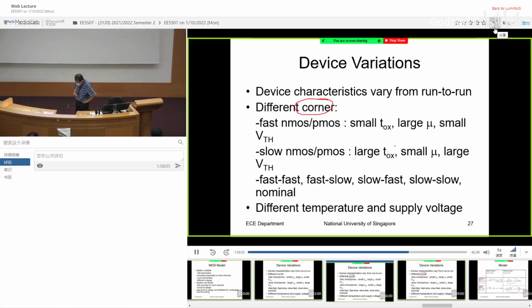And you know that your chip will not operate at only one temperature. So a lot of times, students only run the circuit at room temperature. Now, for an IoT device, they usually consume very low power, maybe milliampere, microampere, that's fine. The junction temperature will not rise very high. So room temperature or slightly higher usually works. But if you are designing a power amplifier, you are dissipating 1 watt. So that will generate a lot of heat. So when you run the circuit simulation, you should run at 80 degrees Celsius, 100 degrees Celsius. Because this is most likely how the circuit temperature is going to look like.